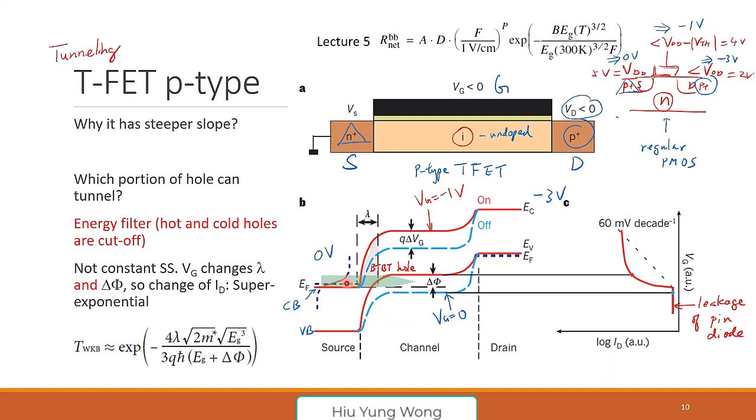Why does it have to be intrinsic? You mean the doping? Yeah. I mean, just think about it, it can be others, right? But if you make it exactly N and let's say this is N plus, then you are going to need to apply very high gate voltage to turn it on. And then you also have a very steep gradient between N and P. So just now you also said that you will have a very steep gradient here. You might have band-to-band tunneling or impact ionization in this region.